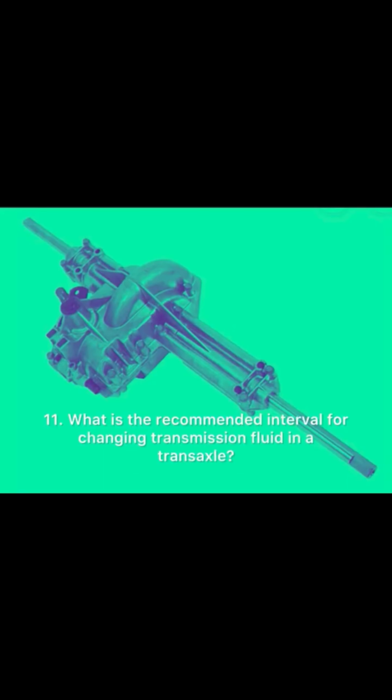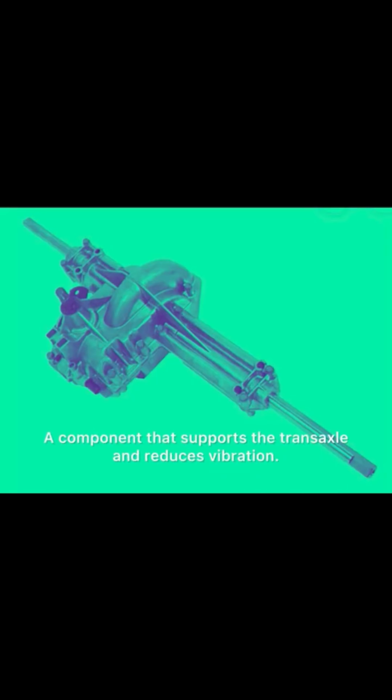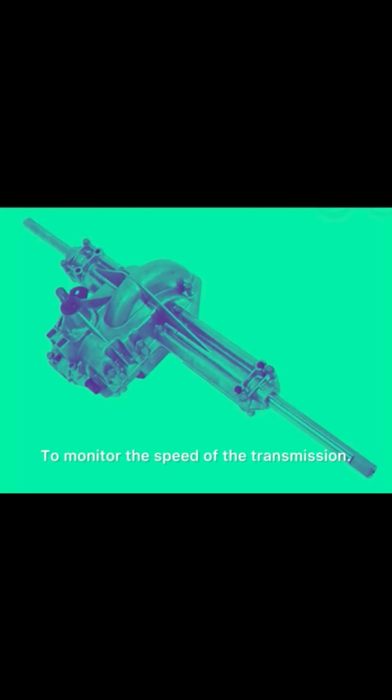10. What is a common symptom of low transmission fluid in a transaxle? Slipping or hesitation. 11. What is the recommended interval for changing transmission fluid in a transaxle? Typically every 30,000 to 60,000 miles. 12. What is a transaxle mount? A component that supports the transaxle and reduces vibration. 13. What is the purpose of the speed sensor in a transaxle? To monitor the speed of the transmission.